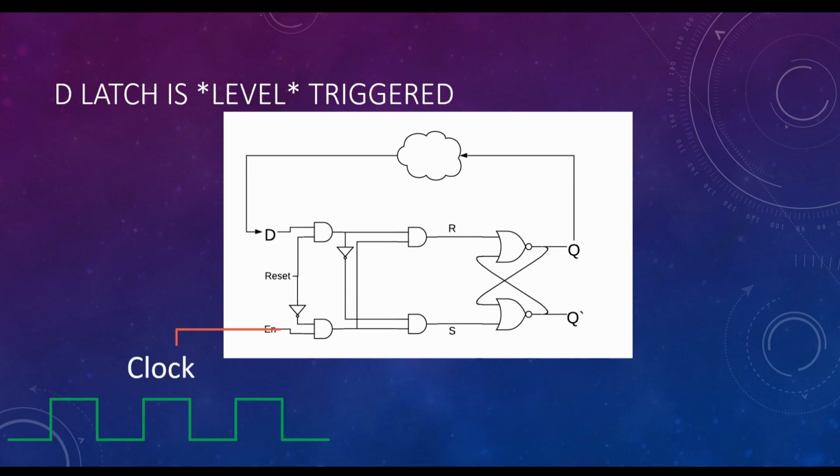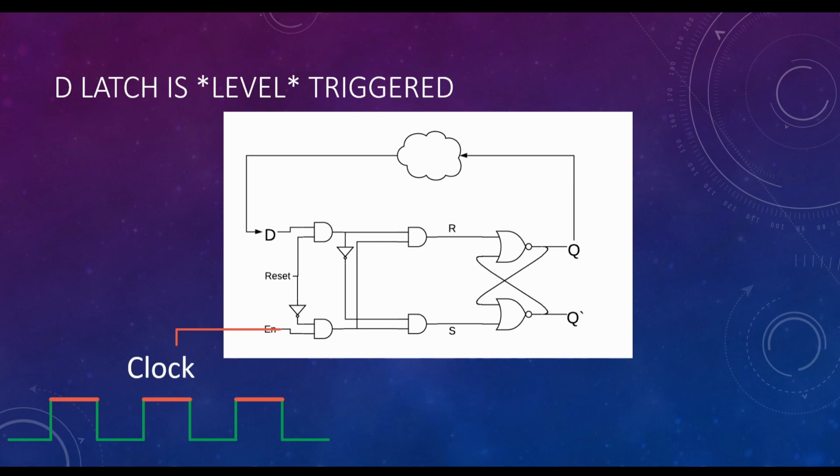And if we connect a clock to control this, and that's what we will eventually do, we'll control sequential logic with a clock, the latch will be active on the high levels. So throughout those levels here that you can see here, throughout this time here, it will be enabled, and that's a long time. So we can still have the same problem that we had before when the system doesn't settle, continues to fluctuate. We have a mitigated problem because on the lower levels, the latch is disabled, but still that's too long. Okay, so we do have control over time because we can disable the latch, but it's not good enough.